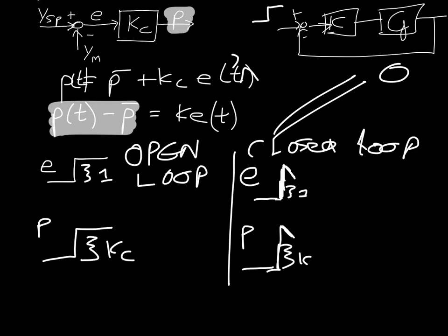But we would like eventually for the error to become 0 again. But as the error becomes less, the impetus for change reduces. And so there's an equivalent less change in the action, and eventually, now I'm going to draw this nice and continuous, eventually we don't quite reach the position that we would want to reach in order for the error to become 0. Now please just note that our target is not necessarily to return to the bias position, because at the bias position the output was the original output that we wanted, right, at time 0. We definitely want the output to be different, but we want the output to be the correct output, which will lead to 0 error. And that's not happening because we're changing.